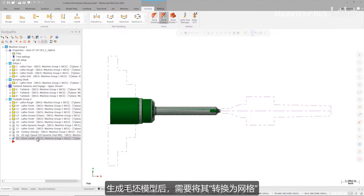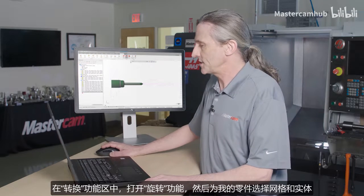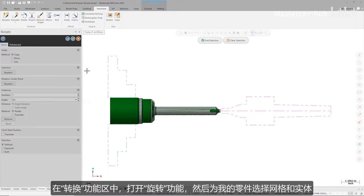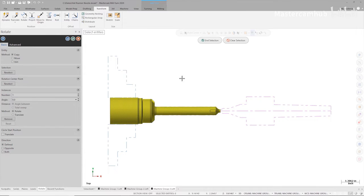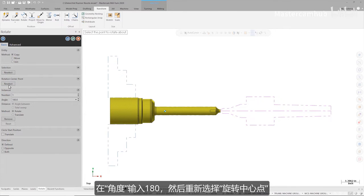Once the stock model is generated, I need to convert it to a P-mesh. Now that I have an accurate representation of my stock up to this point, I need to rotate the solid model of my part as well as the stock model 180 degrees. On the Transform tab, I'll launch Rotate and select the P-mesh and the solid for my part. I'll enter 180 as the angle and reselect my rotation center point.